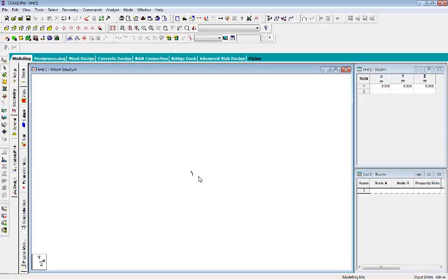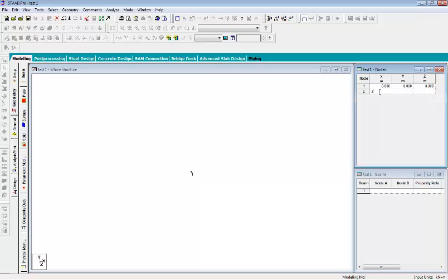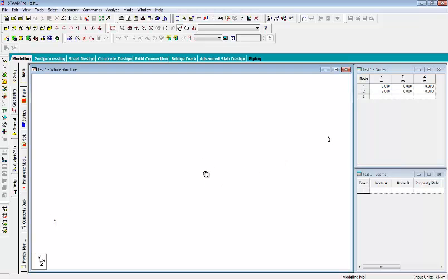Just see 1. Now if we add another node, say at 2 0 0. You can see the two nodes are there. In order to scroll down or scroll up, you just need to roll the mouse wheel. So now we have created our first nodes 1 and 2.